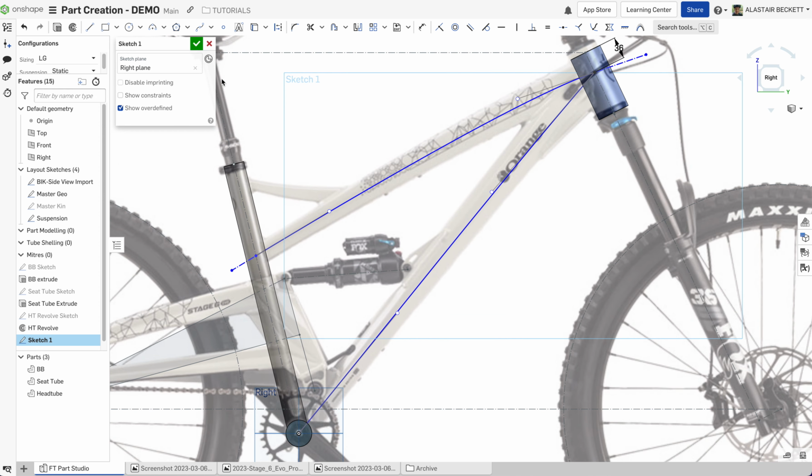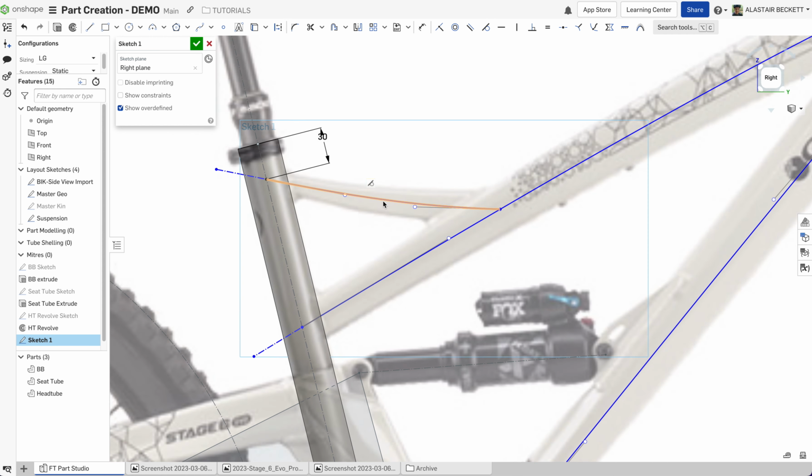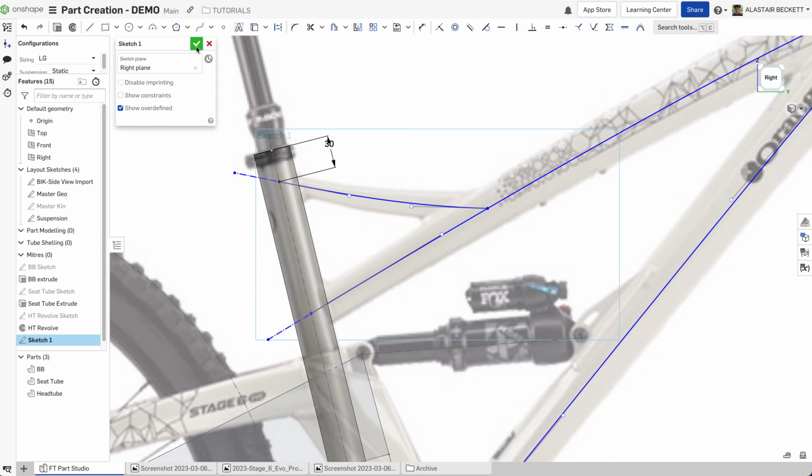And the only other one is this brace. So again, it's like the spline. Try and follow roughly where you think the center line would be. Same story here, and then just add a little bit of curve so that it sits roughly where you think the center line might be. And we will stick a dimension on this so it doesn't move. 30 millimeters sounds good. And then we'll do the same thing and put our construction line here and make it tangent with that line so that we've got it there for later. We shouldn't need one here at this side. I don't think. May regret that.